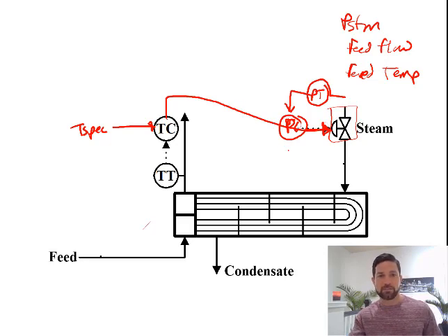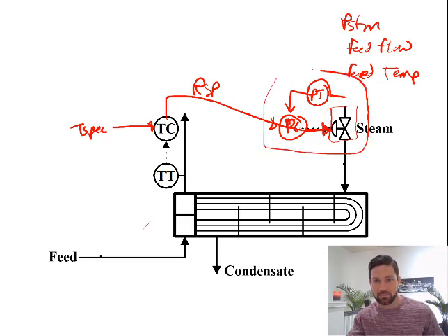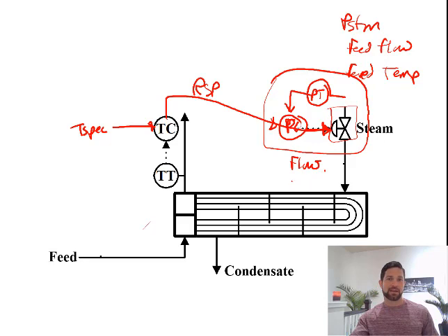I drew this over the feedback control loop because we know that the primary control loop is going to send a remote set point to the inner control loop. So the primary control loop provides a remote set point to the inner controller. We measure the disturbance, which is the pressure of the steam, and change the valve accordingly. So this is going to account for changes in steam pressure. I want to note on this inner cascade loop, I used pressure sensors. You can also do the same thing using flow. It would have the same effect.